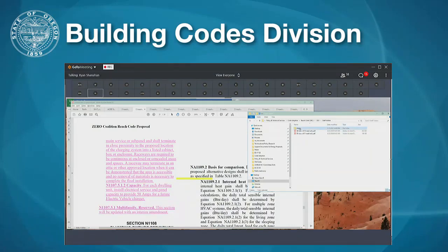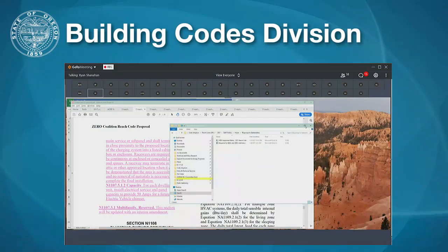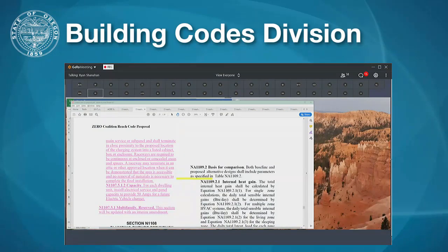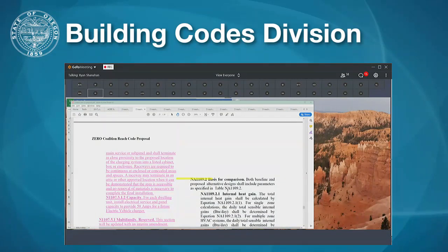This is Ryan Shanahan. I just wanted to chime in, mentioning that I've done some research for this for the Earth Advantage program, as well as making my home future ready for EVs. Essentially this language lines up with what you'd want to do to make a home ready for level 2 charging, which is industry standard, typically aligns with the NEMA 14-50 plug. And I'm fairly certain that you can use a 50 amp circuit with the 50 amp charger like John mentioned.